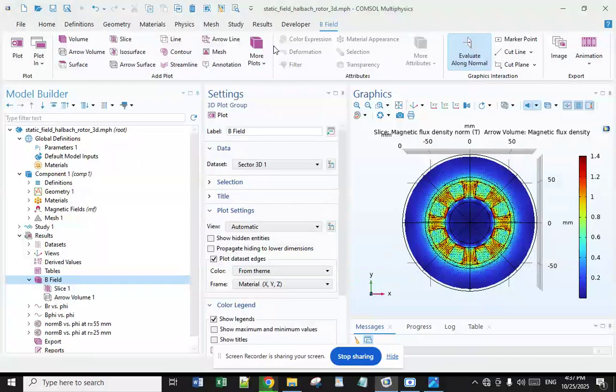This example presents the static field modeling of an outward flux focusing magnetic rotor using permanent magnets. A magnetic rotor, also known as a Halbach rotor. The use of permanent magnets in rotary devices such as motors, generators, and magnetic gears is increasing due to their no contact, frictionless operation. This model illustrates how to calculate the magnetic field of a four-pole pair rotor in three dimensions by modeling only a single pole of the rotor using symmetry.